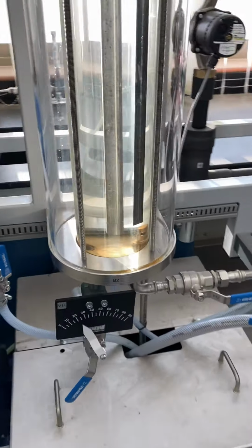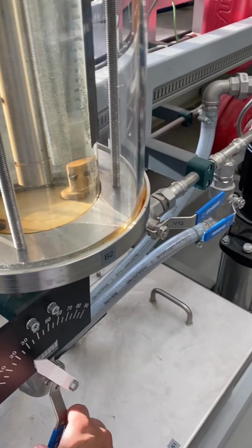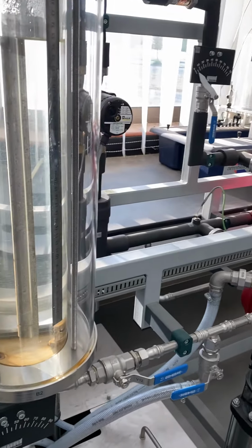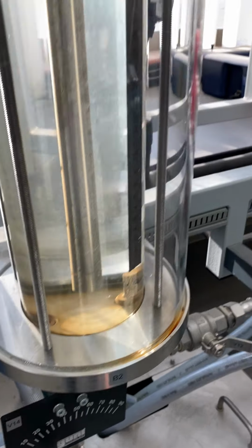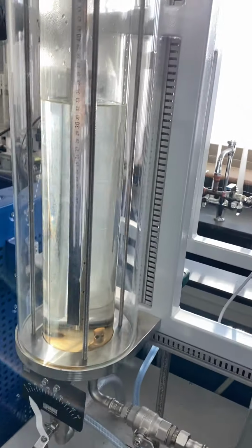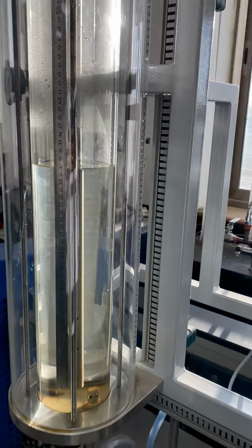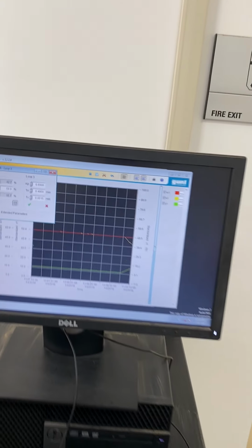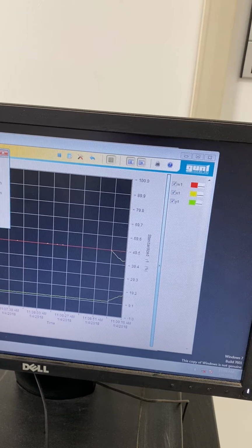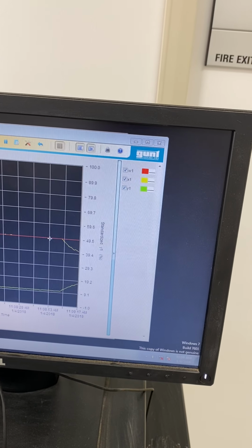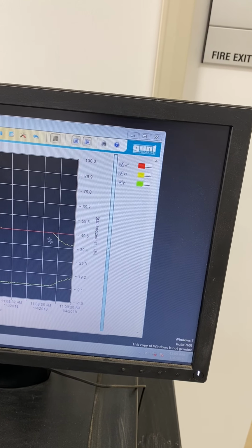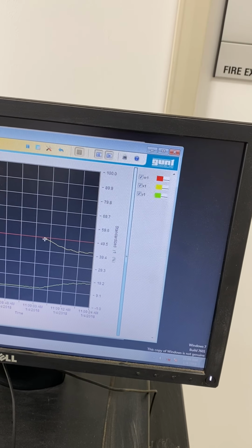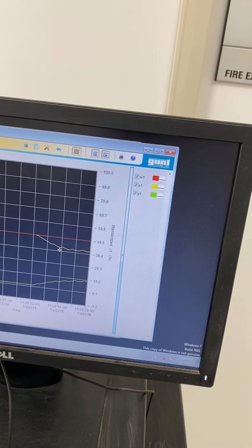Okay, so let's do the following. I will open this valve more. Let's see, I just opened. Liquid level started to go down, as you can see. Okay, so that is a disturbance, guys. I was running in steady state condition and someone opened the valve. So the process value and set point were together here, and the moment I opened V14, liquid level started to drop.